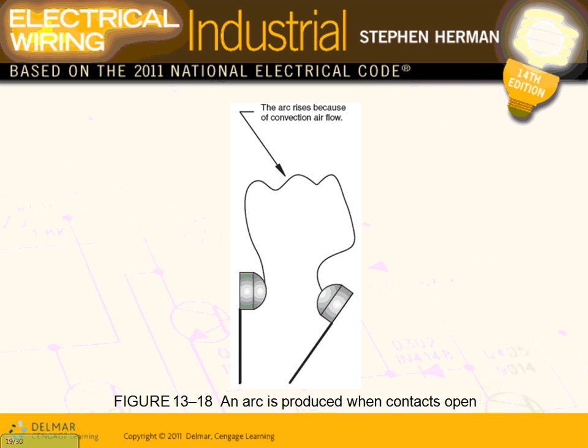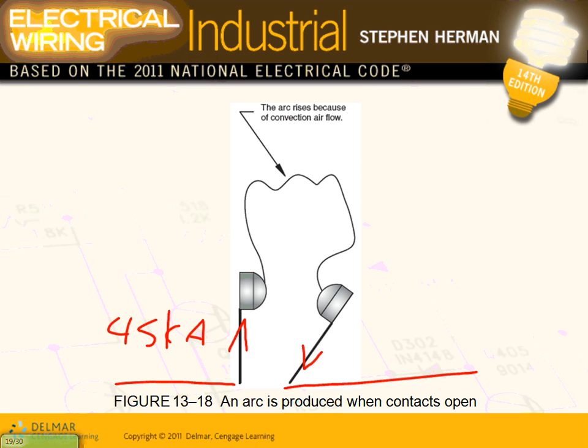How do you extinguish the arc? Here's my 4,000. Now this is a short circuit. I'm interrupting a short circuit, and the short circuit is 45,000 amp, coming to a machine. This is phase A, just phase A, and I'm opening the circuit breaker. When you interrupt that 45,000 amps, it's a huge amount of energy. Just to give you an idea how much power, take the 45K, multiply it by 480, the voltage staying constant, and multiply it by 1.73.